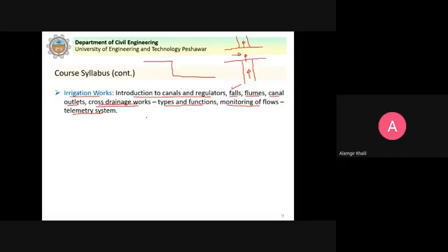So if the depth is shallow, we calculate the average velocity at 0.6 times the depth of water, or the 2-point method where you use the 0.2 and 0.8 times the depth of water and then average. So you can develop the rating curve, which is the discharge versus the depth.